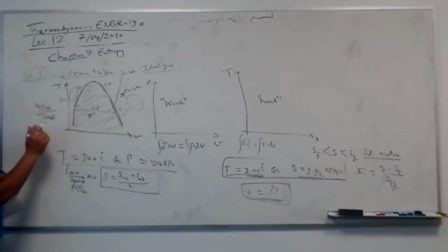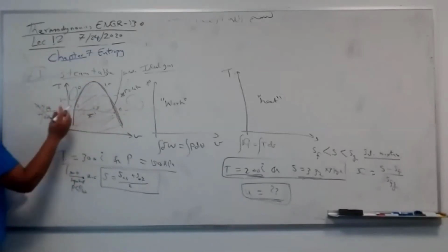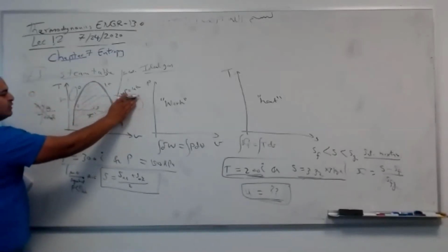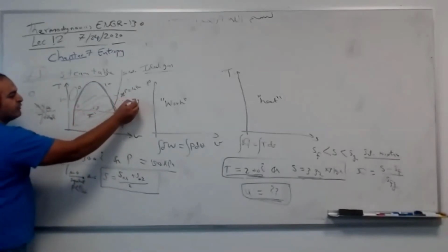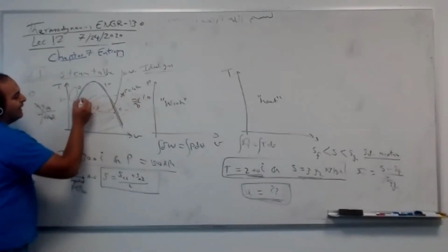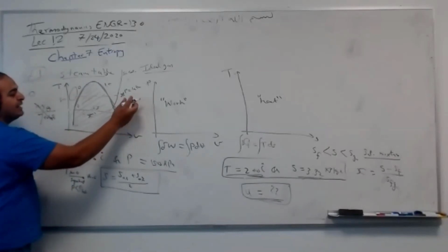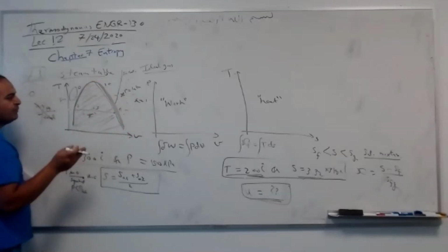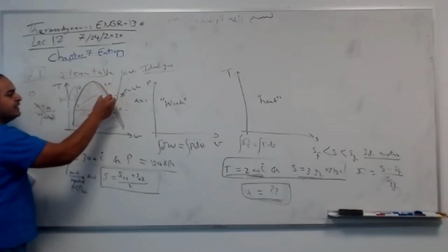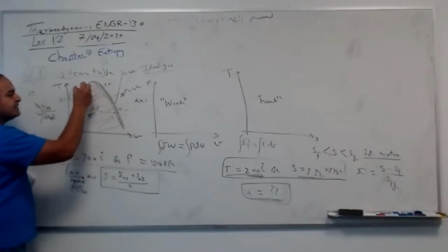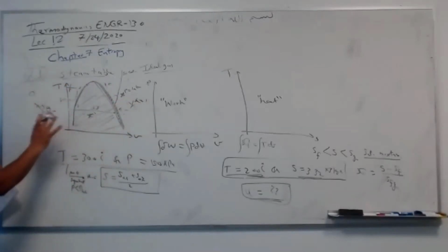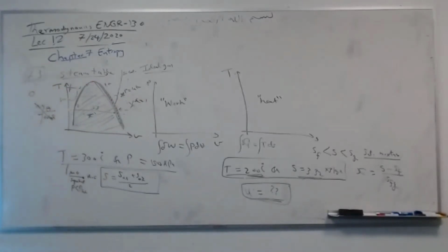I see. So here there is no X. Here, if you just write a dash like this, 0 is sometimes wrong, but 1 is also possible because you can say that's mass of gas over total mass, which is all gas, so it's 1. I don't like this, but you can say that. But 1 means you are on the saturation line. I don't want to make this confusion. X equals 1 means I am exactly saturated vapor. There is no X here at all, there is no X here at all. X only in between.